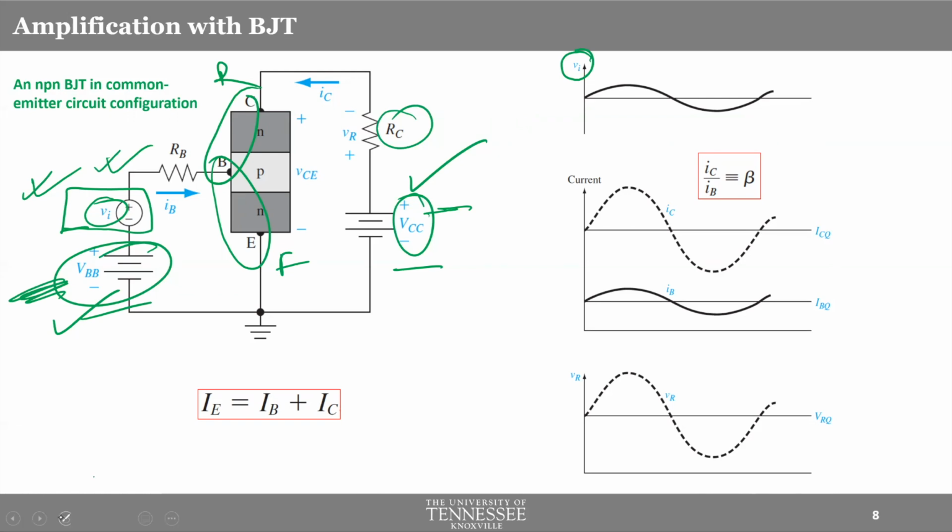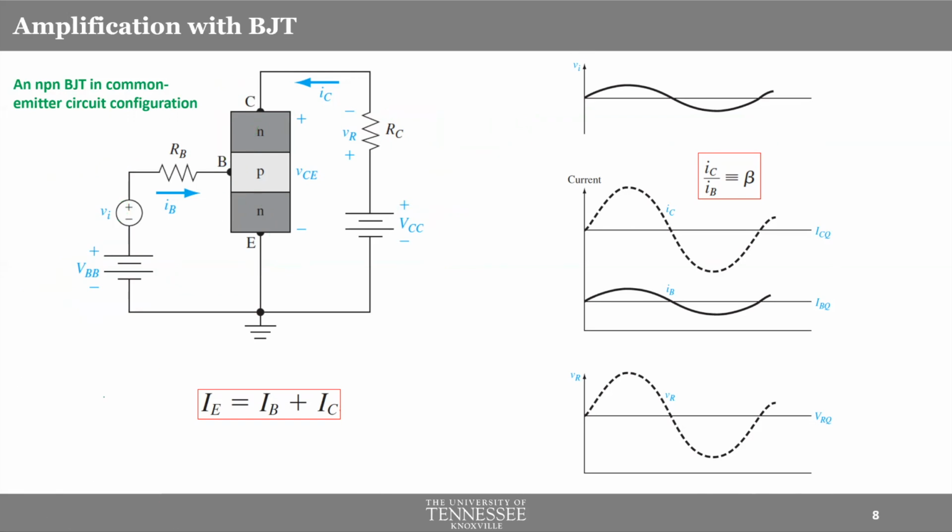That's why the concept of small signal. We will not use that high of a signal to disrupt the entire forward and reverse biasing. So this voltage is low enough or small in terms of amplitude that it doesn't really change the overall forward to reverse biasing. Okay, that's dictated by the DC voltages.